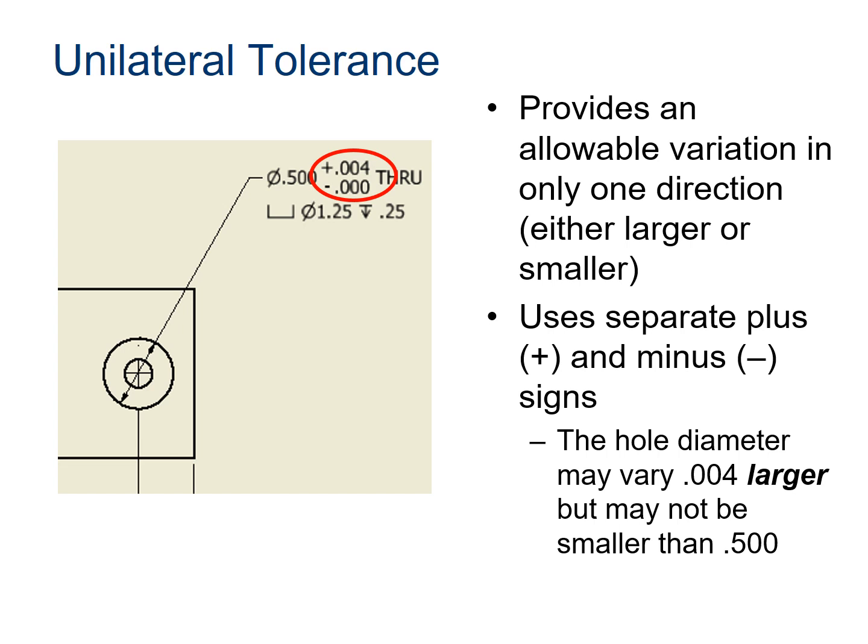I experienced this particular specification when I was working with steel manufacturers. They would specify the thickness of their steel as plus 0.00 something minus 0. So for whatever reason, that's how that industry chose to use their specification. So they always basically manufactured to the low end and then allowed themselves some variation on the high end.